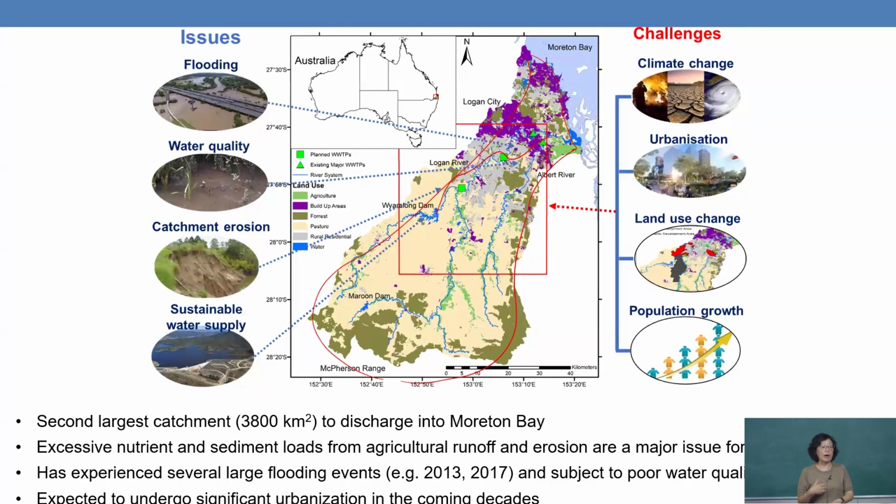So we try to investigate when to release the treated water, because we don't want, when it's high tide, the emitted water to be pushed upstream. We would like to release it in the low tide period, so that it will be diluted and washed away to the Bay Area. And how, when, and what kind of potential risk is in this area, we all want to look at. So that's initially because of this.